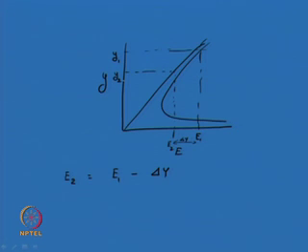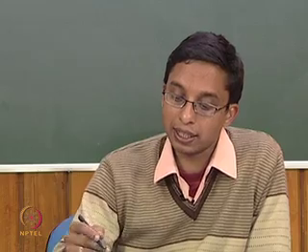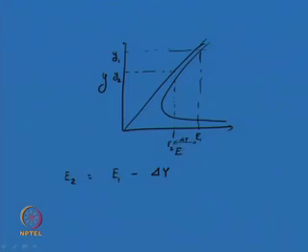So, for a subcritical flow, you will see that due to the change in elevation, due to a hump coming into the picture or arising in a flow, the depth of flow at section 2 will reduce. As the specific energy is getting reduced due to the hump elevation, the height of the water is also reduced subsequently.